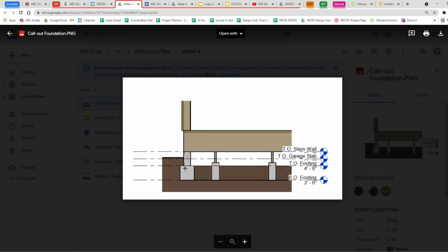What's actually in there? Here we've showed that we have backfilled to a certain depth for the footing. Okay, so you would have had to have made a trench and done all this out and poured the footing and probably formed this, and then you would do what's called backfilling once it's cured, where you fill all this back up with dirt. So this is showing it in a little bit more detail, and we're going to add a couple of little annotations to it. And now you can see that this is really showing itself.